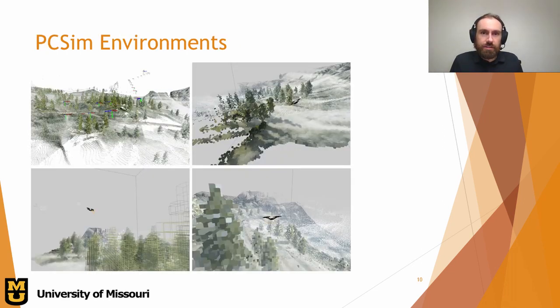And the third simulation environment is one that we've been developing in-house to begin visualizing the agent's knowledge of its surroundings so that we can work on things like high-level control and autonomy. We call it PC Sim, for Point Cloud Simulator, since it's based on reconstructing scenes from point cloud observations. Since AirSim gives a depth image along with a color image, we can use both of these along with the known camera pose to perfectly reconstruct a point cloud from the current drone position.